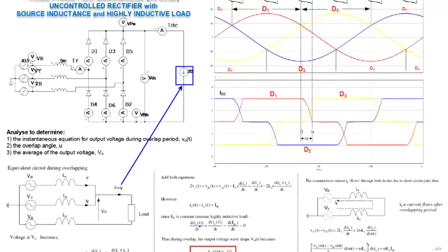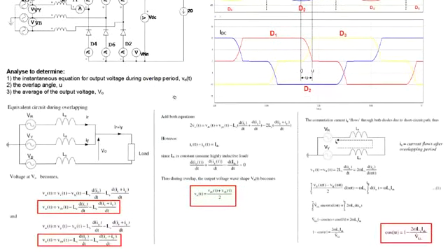So we have diR over dt plus diY over dt equals to diDC over dt equals to 0. Now since iDC is constant, you substitute that diDC over dt into these equations, then you will get the output voltage, the Vout here actually equals to (VRB plus VYB) over 2.